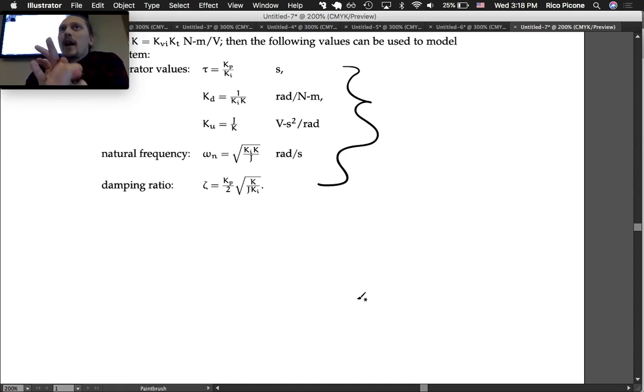Remember, if you drive any current through a resistance, it generates heat, right? And so the more current, even though the winding has low resistance, hopefully, usually it's like a couple ohms for the whole thing. That's enough when you have significant current running through it to generate quite a bit of heat. So it will generate some heat, and that's the other loss.